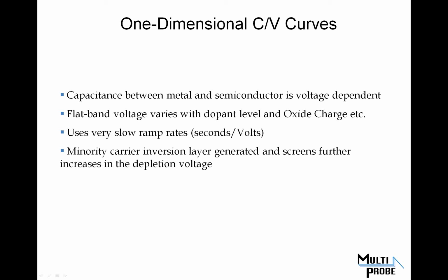Whereas in these structures which are connected up to transistors, the capacitances are, like I said, femtofarad levels, or just sub-femtofarad, which is hundreds of attofarads. And so the signal to noise can be not so bad. That's how we're able to do such measurements.